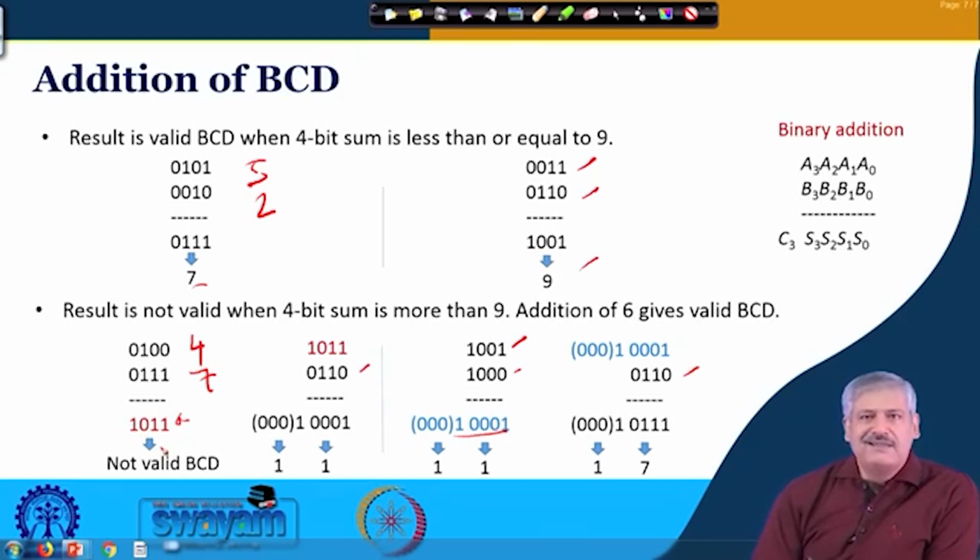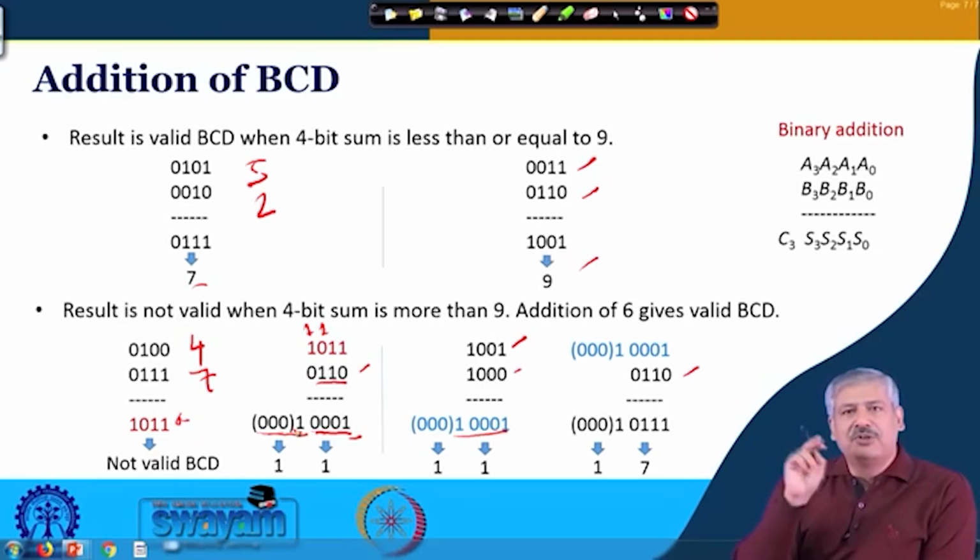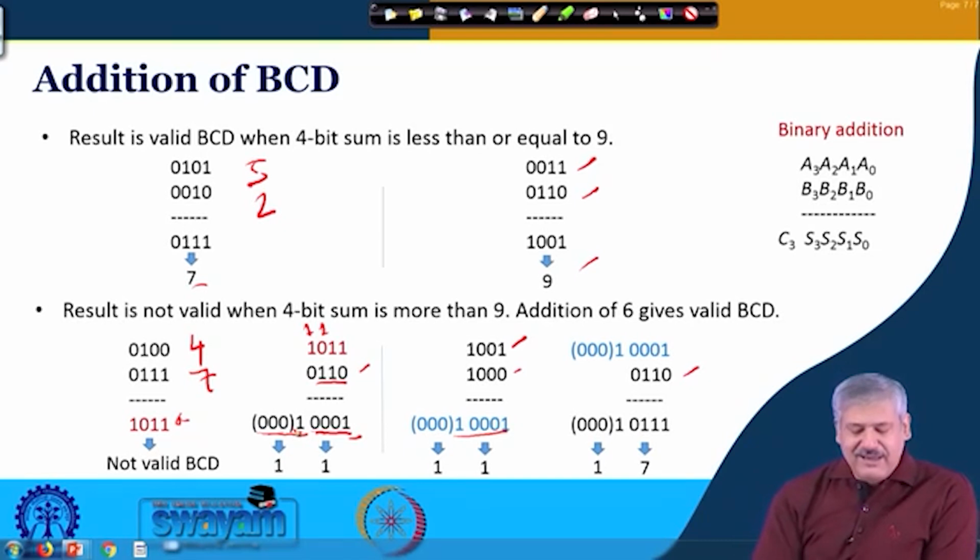So, this was 1011. When the result is more than 9, you have to develop a logic circuit that will add 0110. If you add it up, what will happen? This is 1, this is 110, and there is a carry, which is added with 1 to give 0, and there is a carry with 1, 0, and this is 1. So, this is now a proper BCD coded representation of the result, and where there is a 1 you put leading zeros, which do not alter the value. So, this is 0001, one BCD number, and the corresponding decimal is 1, and 0001 is 1 and this is another number. So, 0001, 1, 1. If you take it to a display device through these 4 digits, which convert to a 7 segment display driver, the display device will show 1 and 1, which is 11, and which is the correct result.